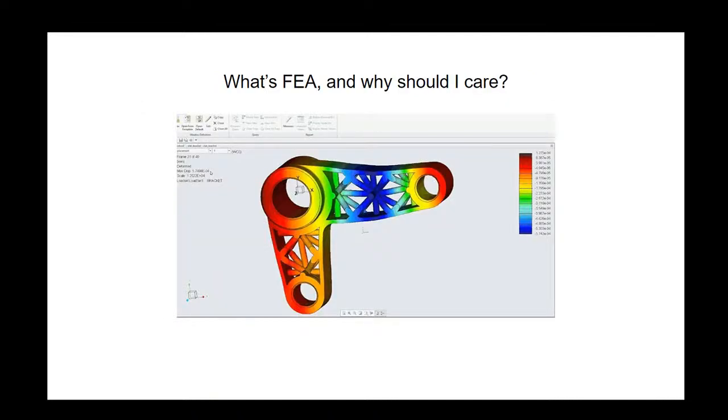If you're interested in using lattice structures in your design, you should probably be interested in learning FEA as well, because the only way you can know if a lattice design will be effective is to test it. Obviously this could mean trial and error of building prototypes and physically testing them, but that can be really slow and expensive. This is why engineers use FEA to simulate how a material will react under certain conditions prior to doing any physical prototyping.